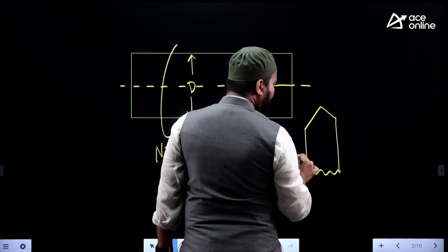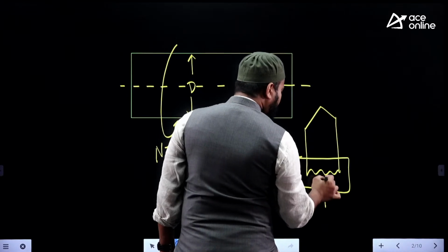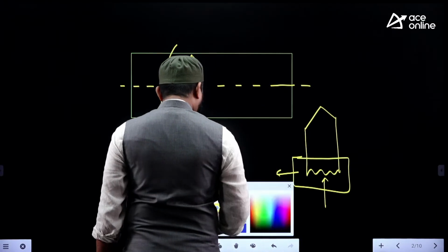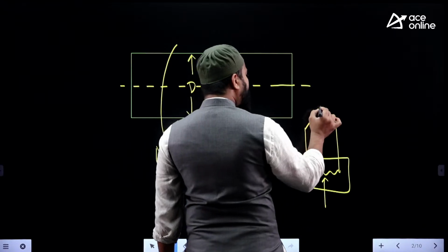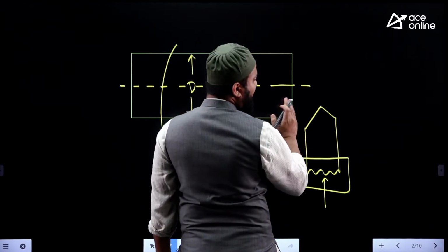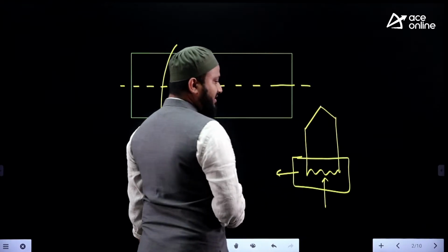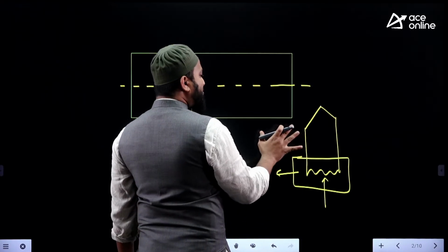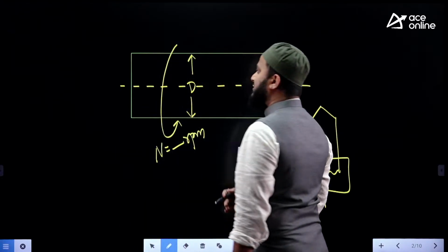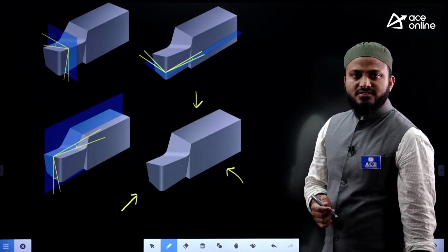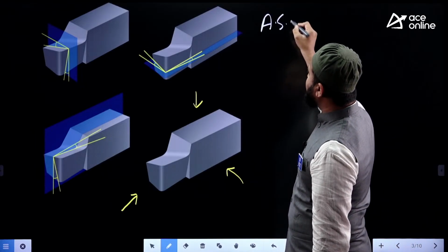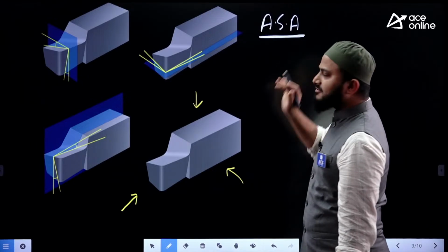In this tool geometry, there is a theoretical tool and even practical tool geometry conditions. In theoretical tool geometry we draw the sharp wedge shape without any curvature, but still we show the side cutting edge angle and end cutting edge angle, and the projection of the tool in the front view, side view, and top view. These are the figures where we discuss the ASA tool signature initially for the definition of the angles.